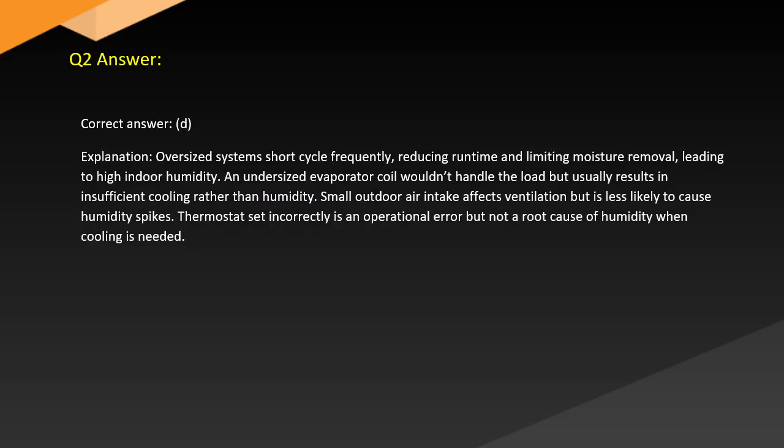Answer. Correct answer, D. Explanation. Oversized systems short cycle frequently, reducing runtime and limiting moisture removal, leading to high indoor humidity. An undersized evaporator coil wouldn't handle the load but usually results in insufficient cooling rather than humidity.